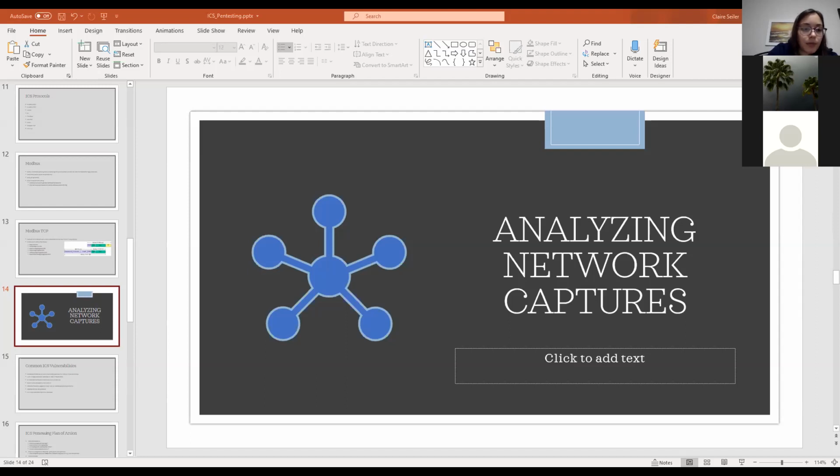If you remember how those packets were formed, it sends a function code and it sends data along with this header, which includes transaction identifiers, protocol identifiers, length, and unit identifiers. What we always want to focus on is that function code, because that tells us what's going to happen, what we're requesting from the PLC. So whatever this workstation is requesting from the PLC.